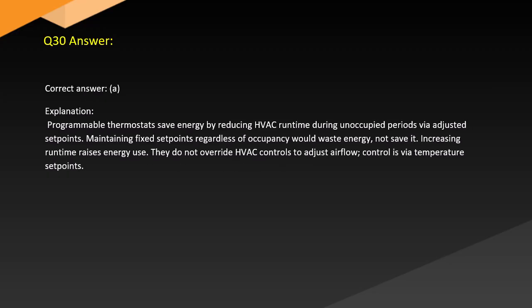Answer. Correct answer: A. Explanation. Programmable thermostats save energy by reducing HVAC runtime during unoccupied periods via adjusted set points. Maintaining fixed set points regardless of occupancy would waste energy, not save it. Increasing runtime raises energy use. They do not override HVAC controls to adjust airflow. Control is via temperature set points.